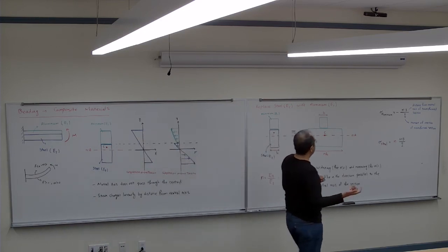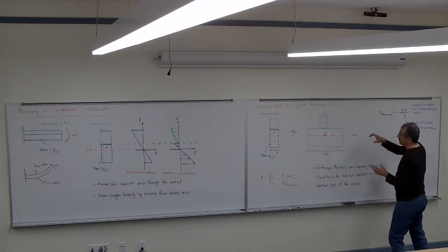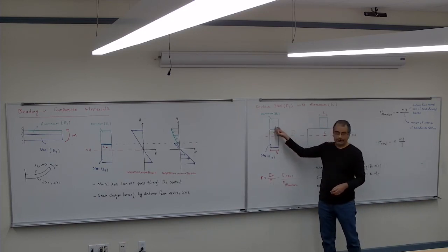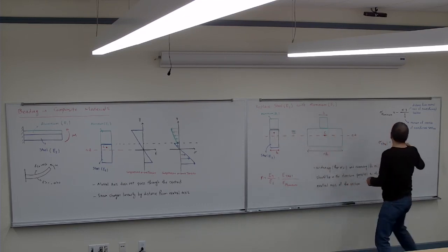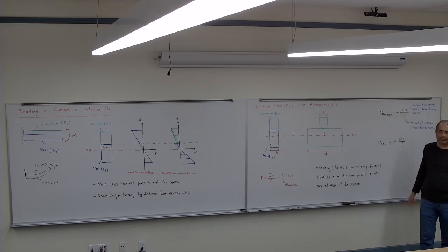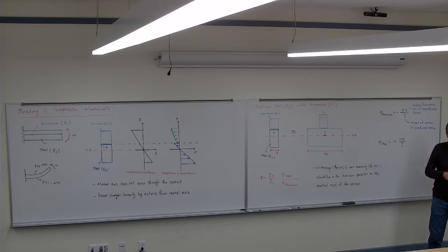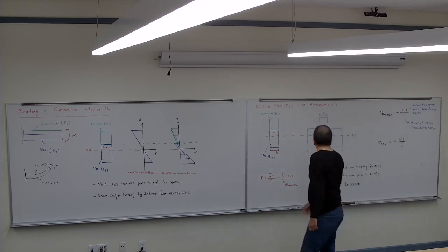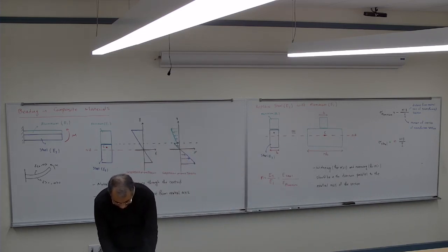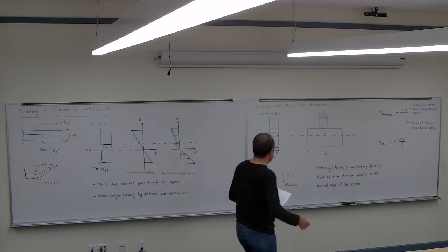So just remember, very quick, that if instead of transforming the steel, I transform the aluminum, I change the aluminum to the steel and make it smaller, this end goes from here to there. Because the steel is not changed, the aluminum part this time changed, so you're gonna multiply the aluminum section. So whatever section you transform, you multiply it by n. This one is gonna be always like that.